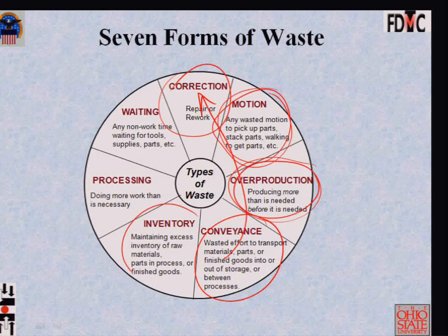Then of course there's the classic inventory. Raw material inventory, finished goods inventory, which of course is here. But then the easiest opportunity in terms of inventory waste is work in process. And therefore, Kanban lot sizes, the buffer inventory that theory of constraints promotes. These are examples of controlled amounts of inventory, and as long as you have that much inventory in the system, you do not produce more work in process. So this inventory really is about work in process. One work center can produce faster than the work center which will receive its work, so it just keeps on producing. In effect, what happens is its output goes into queue at the receiving work center, which is slower, and therefore you have a work in process waste.